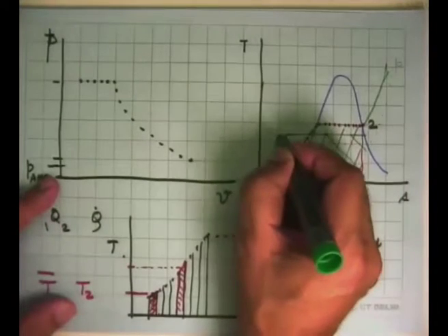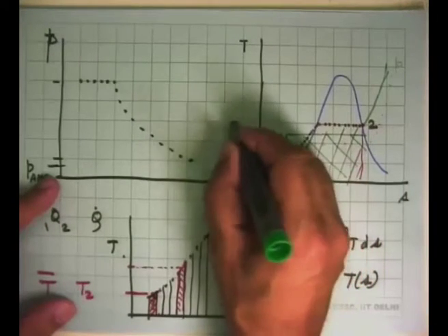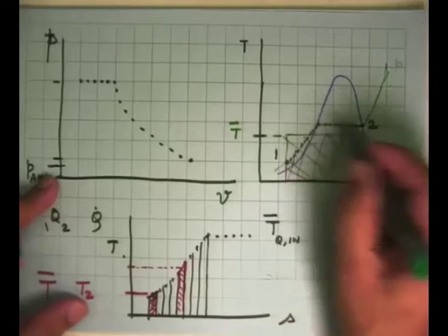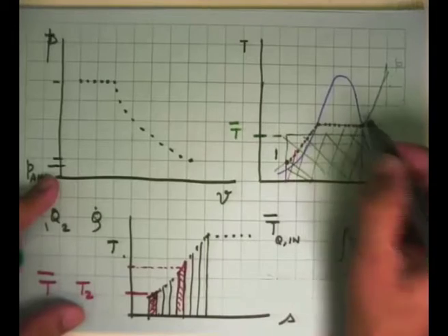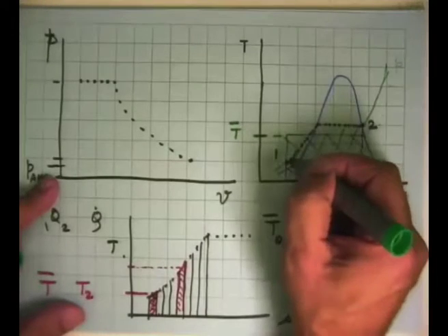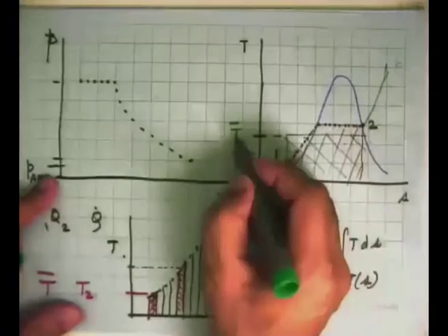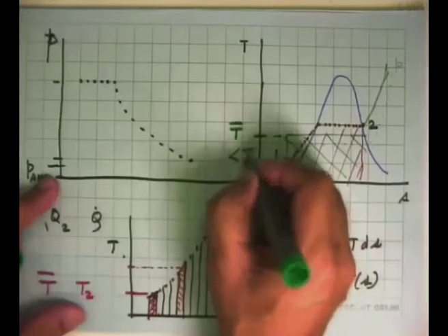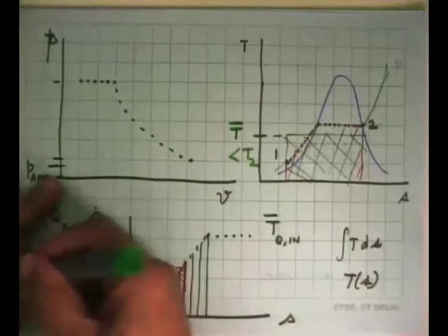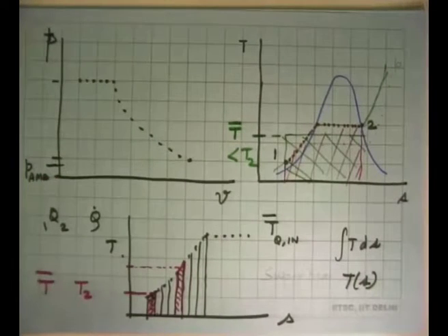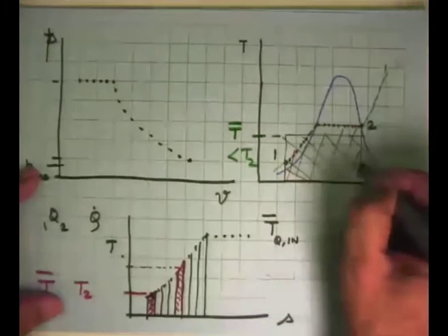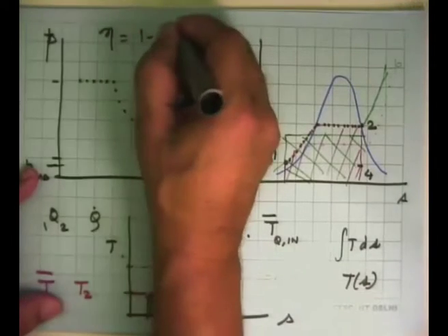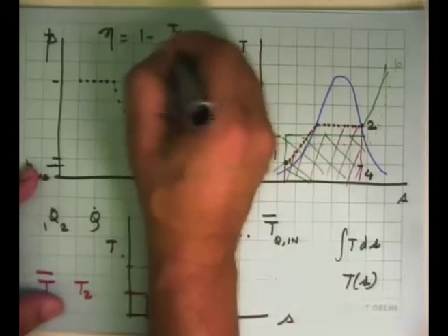But now what we have learned is that this is the average temperature at which heat transfer takes place in the process 1 here and here. And that is to be expected because now we are adding heat at a lower temperature. So T bar, this average temperature, is now less than T2. And so the Carnot cycle efficiency, which was entirely dependent earlier on T2 and the state here, which was T4, there the efficiency was 1 minus T4 upon T2.